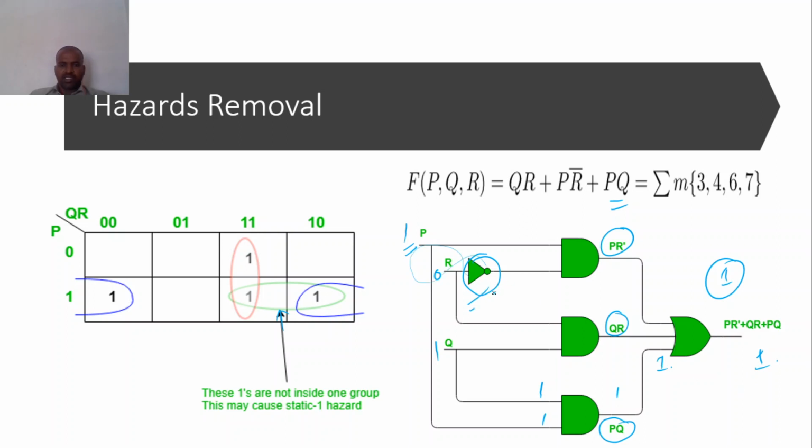So whether this NOT gate is having delay or not, nothing to worry. With the help of this added AND gate, it will produce the result in a very quick manner because here AND gates number 1, 2, 3 are not having any delay. So we are getting the output in a fraction of time. Hence the hazard is solved. That is, the static hazard is solved.